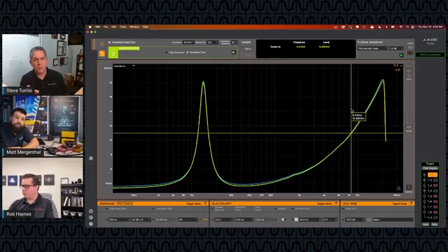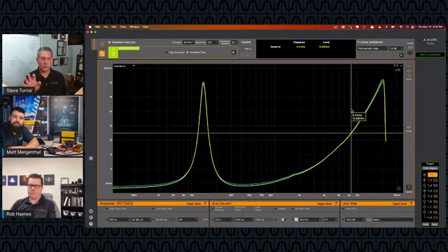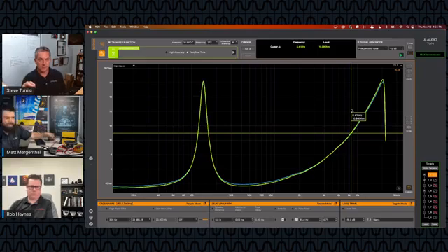If I understand right, Matt, the method you've shown so far, the TRS, the phono jack, the 1/4-inch plug with the alligator probes, straight up 2-wire, the signal for that to drive the speaker is all coming from Max. Correct. Right. And then for the 4-wire that you just demonstrated, the current is coming from that same probe, but now the voltage is being measured from the speaker side as a separate measurement. Right. It's being measured through that RCA cable.